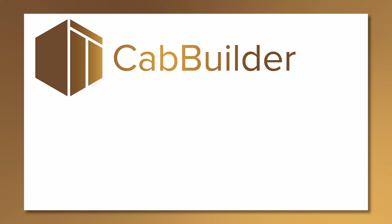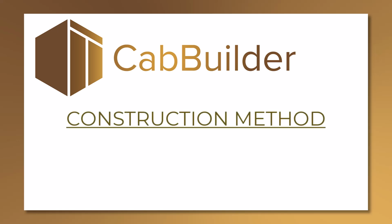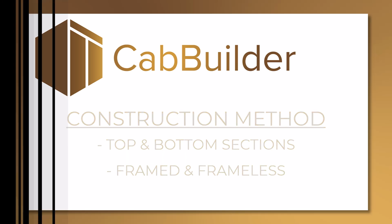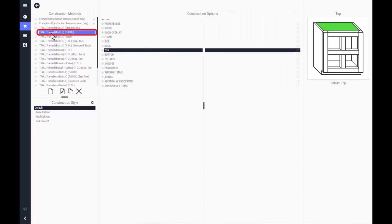The cabinet construction method determines the default cabinet behavior and how it gets converted into the subsequent cut lists. This video will focus on the top and bottom sections of framed and frameless cabinets. Let's begin with the top of the framed cabinets.